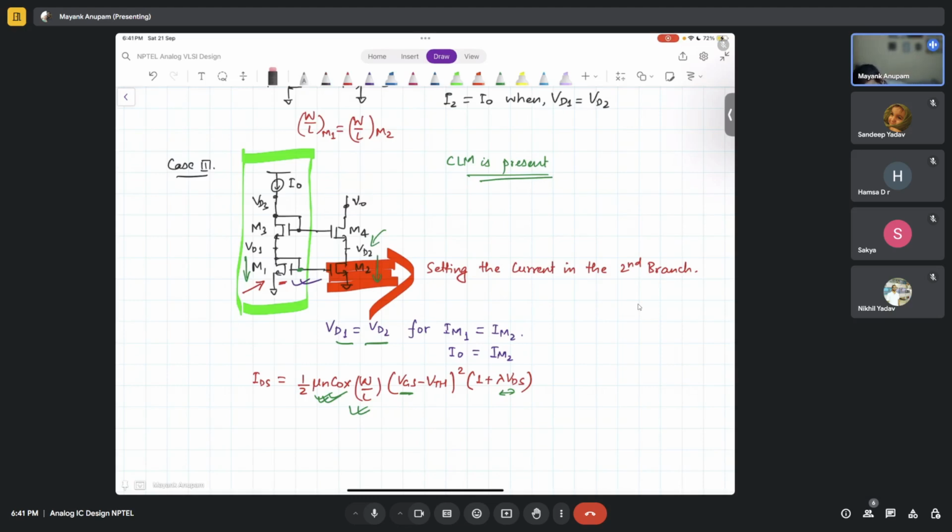So because this is connected to some load, not just RL, it can be any load. And based on the load condition, the currents and the voltage V naught can change here, and because of which VD can change here, right? The drain voltage can change. So that is why it is not really possible to ensure that the drain voltage for both the MOSFETs is always the same, right? However, I'm not going to that.